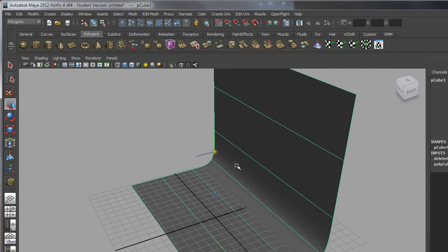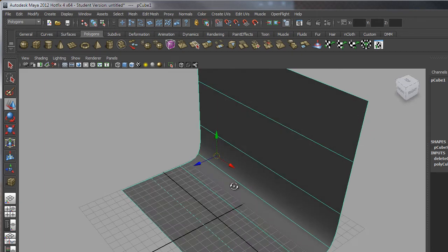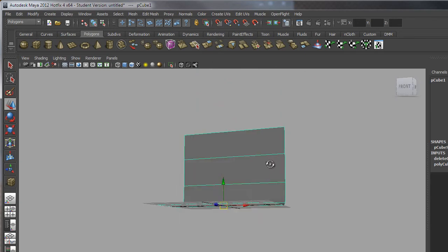Now what this does is allows me to move the position of an object's pivot point. Okay, this location here. What I'm going to do is click and drag in the little yellow circle in the middle of the manipulator handle. I'll just shift this across so we can see it a little bit more. I just want to grab that yellow handle and drag it to the middle of the grid. And you'll see that because snap to grid is switched on, the handle will actually click from one grid square to the next. So we just want to place it here in the middle. And then you can let go of the D key, and then you can turn snap to grid off.